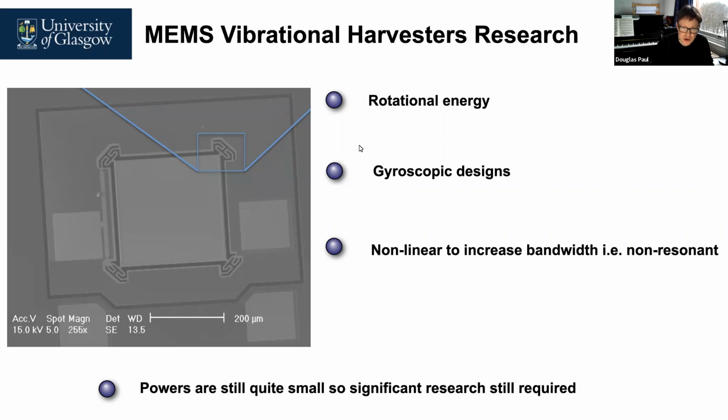There's also been gyroscopic designs, but the real problem I spoke about earlier, and one of the reasons why vibrational energy harvesters are not much more ubiquitous and used for many more applications, is that they're typically designed to be quite wide bandwidth, so they have a lot of applications with the resonant frequencies. That gives you, unfortunately, a very low vibrational to electricity transduction coupling mechanism.